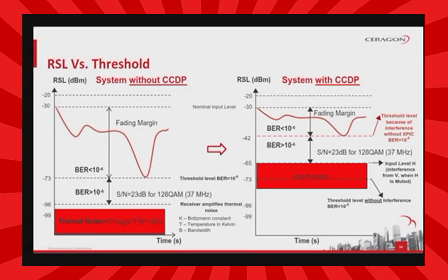Let's present a different perspective on the cohabitation of more than one signal on the same channel, with a different polarization. Presented here you can see a comparison of a system where no interference on the same channel is observed, on the left side diagram, and a system where we can observe a second polarization being used on the same frequency channel, on the right side. The noise rise observed on the right side is due to the cross-polarization interference when we add the vertical polarization to the same channel that was using the horizontal polarization. In our case, for these specific conditions, the interference creates a noise rise from -96 decibels all the way up to -65 decibels. This example comparison allows us to understand the need for an X-PIC mechanism.